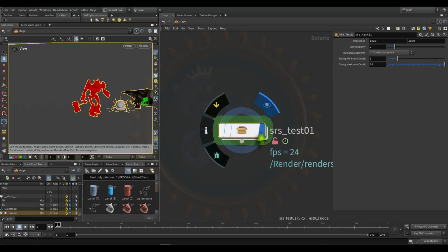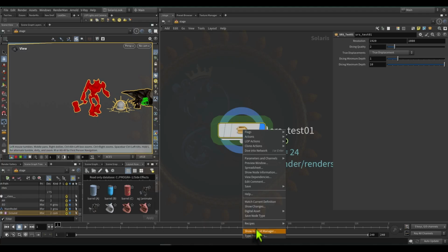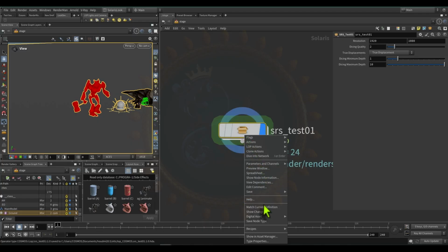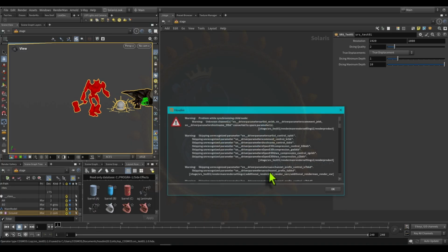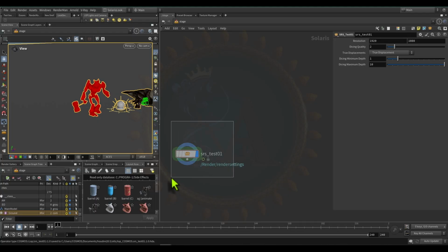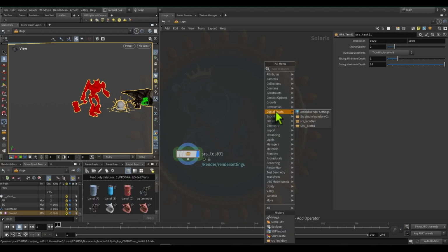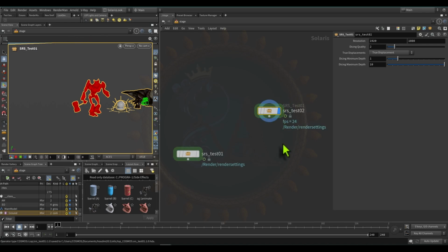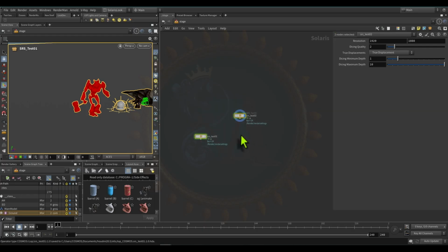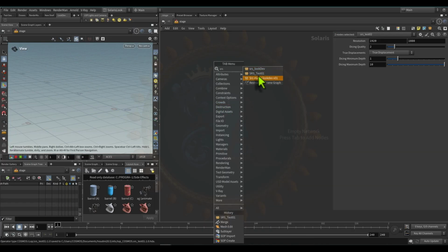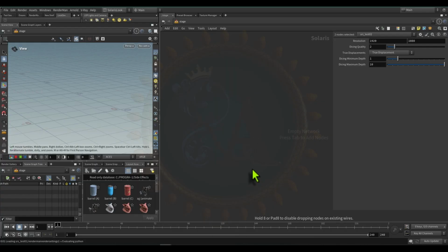If you want to store it on your disk, right click and say this node type, it will lock. Then match current definition. It's done. So if this is done and you want to recall it, you can check it in your digital asset. It's created. I'll delete all of them. Okay, nothing is there. So just press tab and search for the one I recently created. Ready.